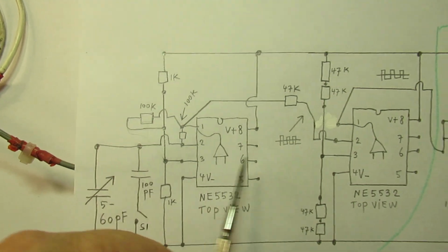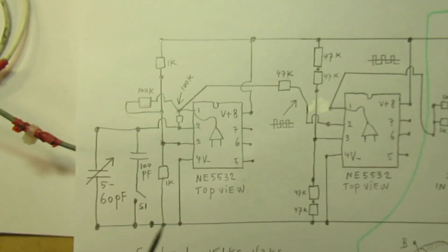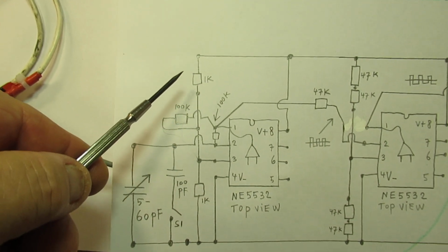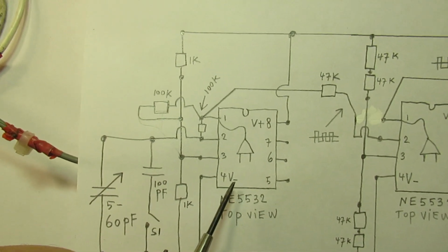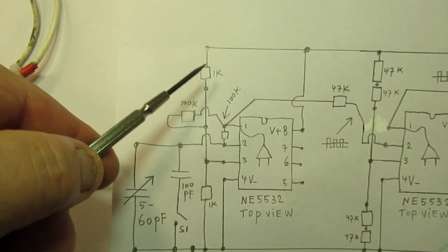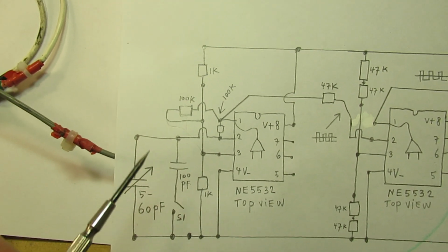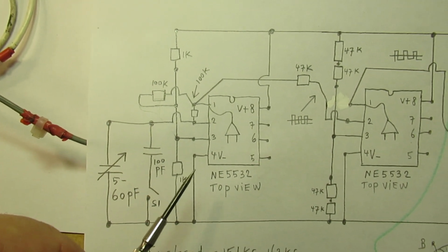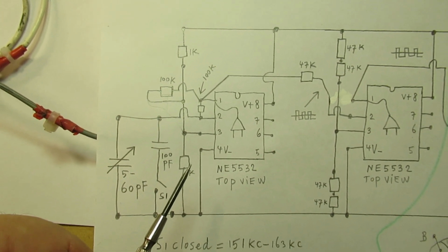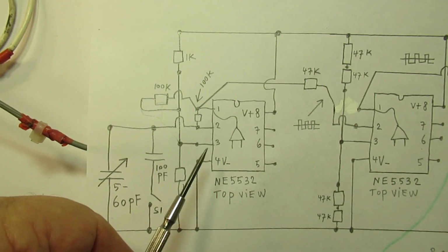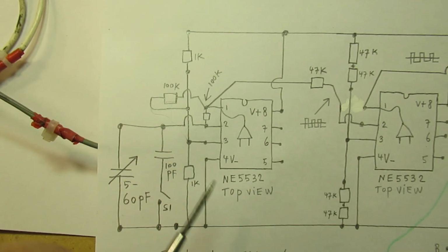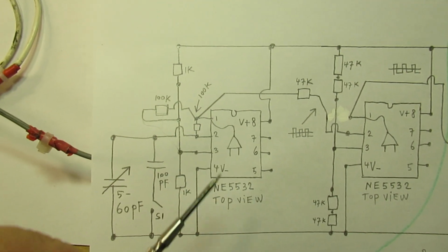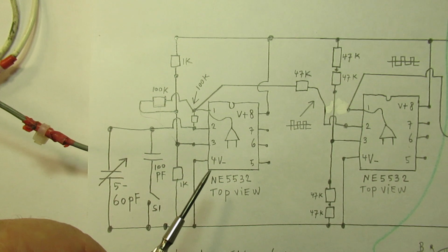The first op-amp, second op-amp, I had to change on pin 3 the values of these two resistors. They set in a certain way a kind of voltage here, and make it so that this circuit can work on only one voltage, so I don't need a double voltage supply.